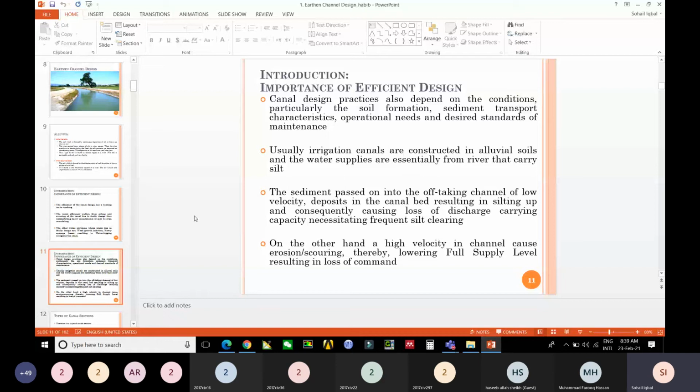If you do not remove the silt, then the bed will start to disintegrate, and there will definitely be a great loss of water, because the channel is full of sand, suspended particles, or any accumulation, be it soil or any other material. How efficient your channel is depends on how much discharge you can achieve at the outlet.